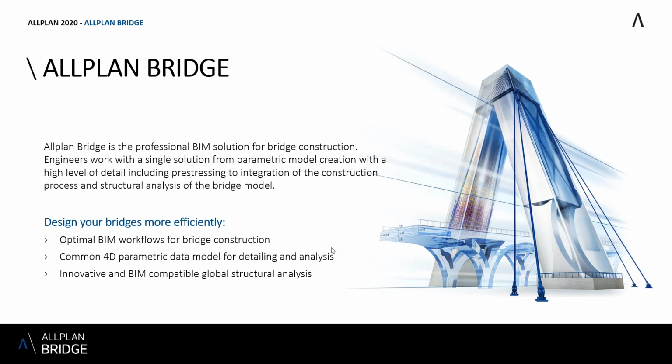However, the team that is developing Allplan Bridge is very passionate, and they went very fast and very far. They made this 4D parametric, meaning that even within a drawing software like Allplan, within this plugin Allplan Bridge, you can simulate the phases of construction. They also implemented analysis, not only to determine the cross-section capacities, but also the forces, and now they're working on the capacity of the elements.